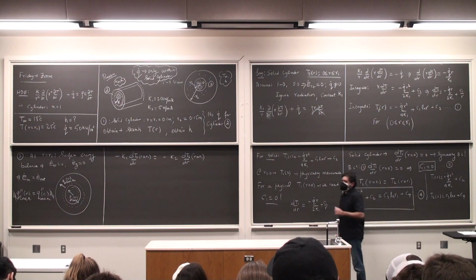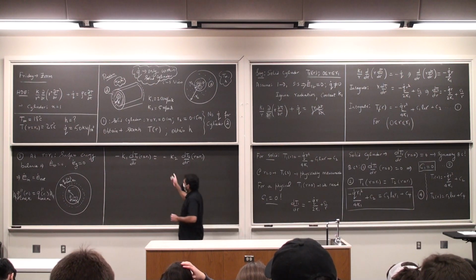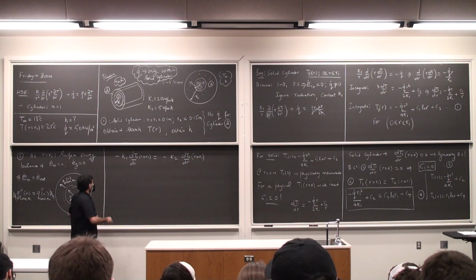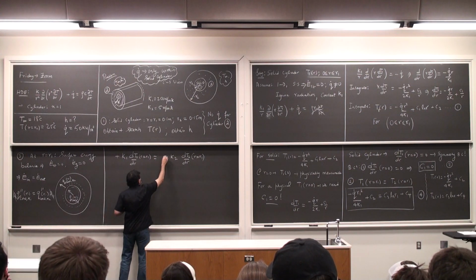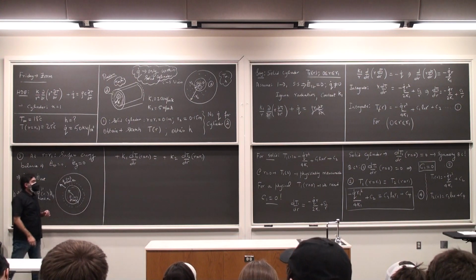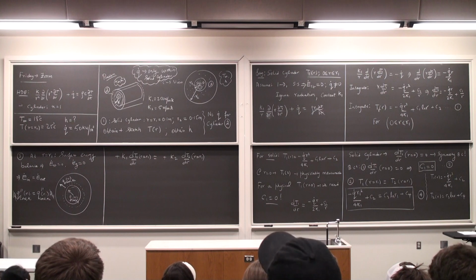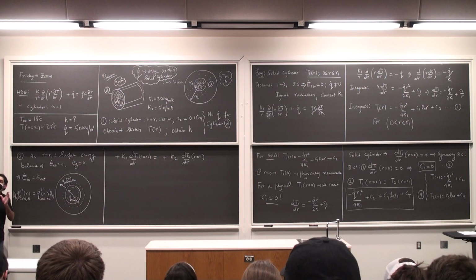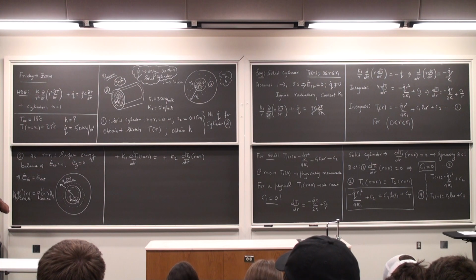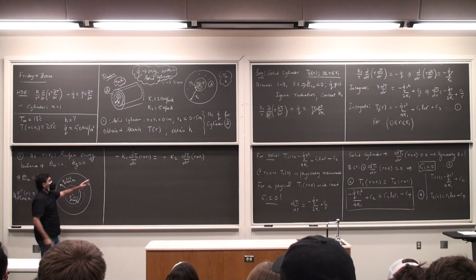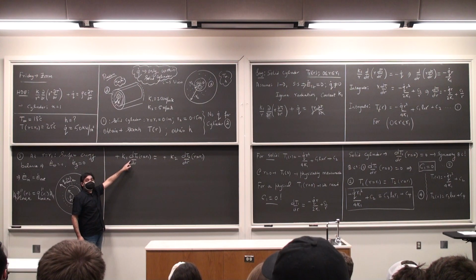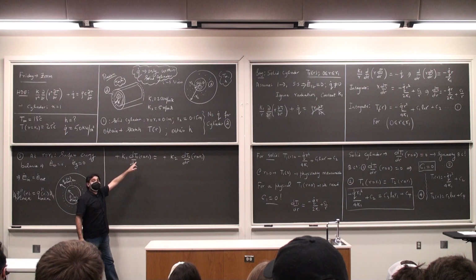Before we go ahead, obviously the negative sign vanishes, so I can say this is plus, this is also plus. I'm just preempting what the slope discontinuity could be at R equals R1. This is the slope as I go through the material of thermal conductivity K1 at R equals R1.